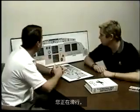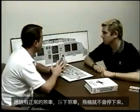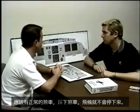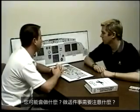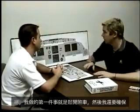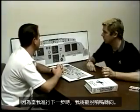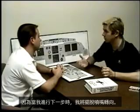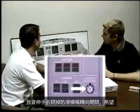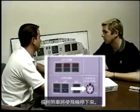New day, you're taxiing out, captain goes to do a brake check, should have normal brakes, applies the brakes, and the airplane's not stopping. What might you do? And what are some cautions to doing this? Well, the first thing I do is get off the brakes, and then I'd also make sure I don't have any steering inputs in there, because when I do the next step, I'm going to get rid of my nose wheel steering. I'll reach up, turn the anti-skid nose wheel steering switch to off in hopes that the alternate brakes are going to stop the aircraft.